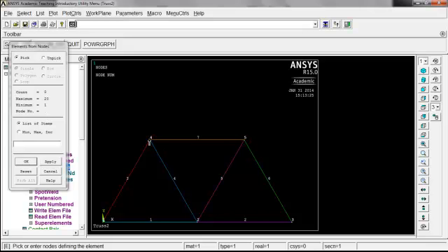The direction in which you click, so node 4 to node 5, the orientation doesn't really matter because ANSYS is doing all the work of setting up the equations, and the results would be the same either way you clicked them. If I clicked 4 first and then 5, or 5 and then 4, it wouldn't matter.